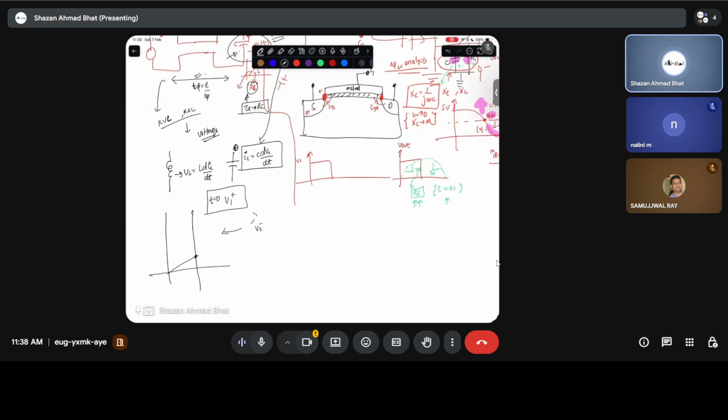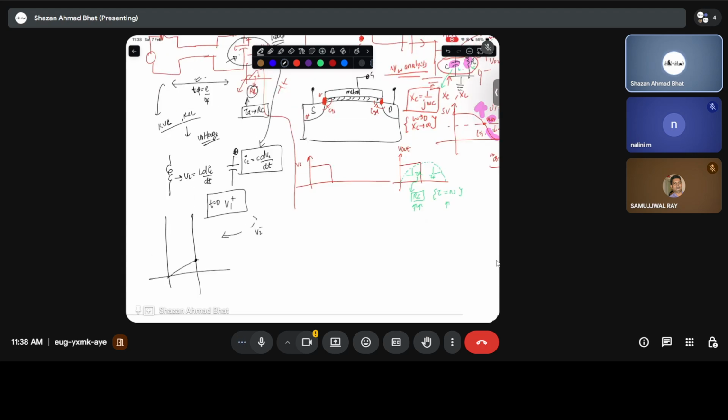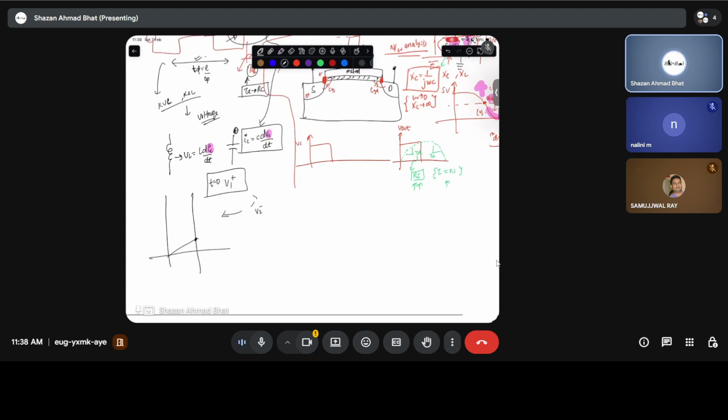But the difference here is that this impedance, or I should say the reflections of this particular wave, will now be time dependent. Why? Because these quantities are time dependent now. These are the voltage across the capacitance, or the current across the inductance. So these are time dependent things. Why? Because that's what I talked about.